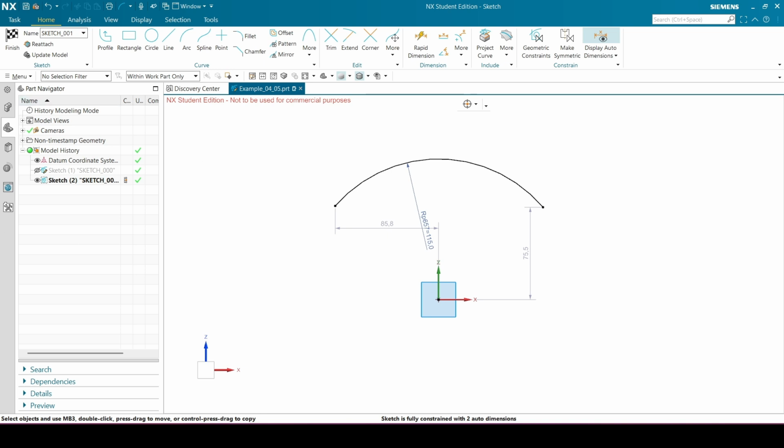Especially for a sketch like this where there are a lot of dimensions, it's good to make sure that you don't miss something. Okay, then I'm going to put in the 91 millimeter radius arc, and that one is tangent to the 115 millimeter one at the topmost point. Its exact center point isn't given. It's just in line with the 115 millimeter one.